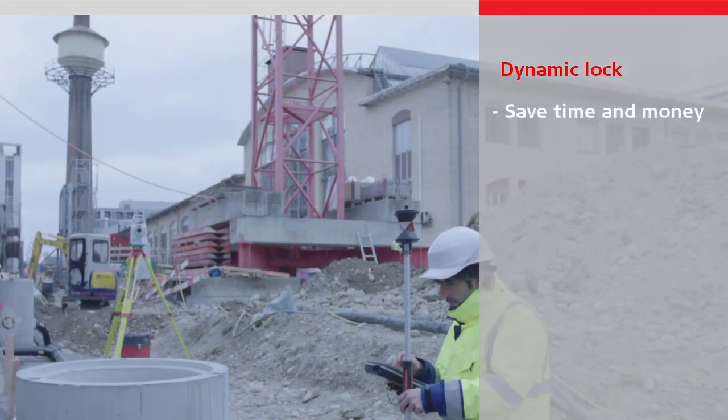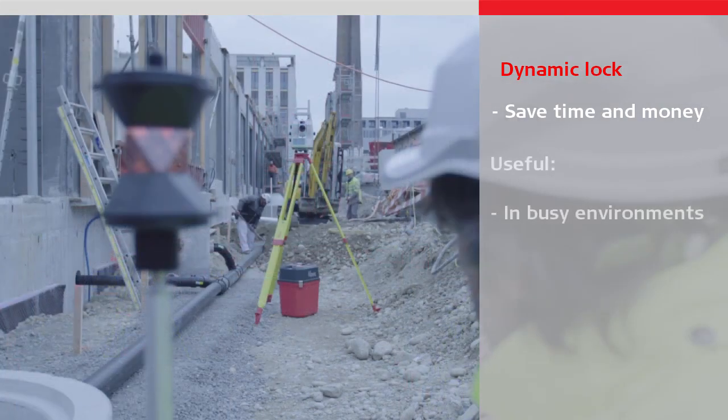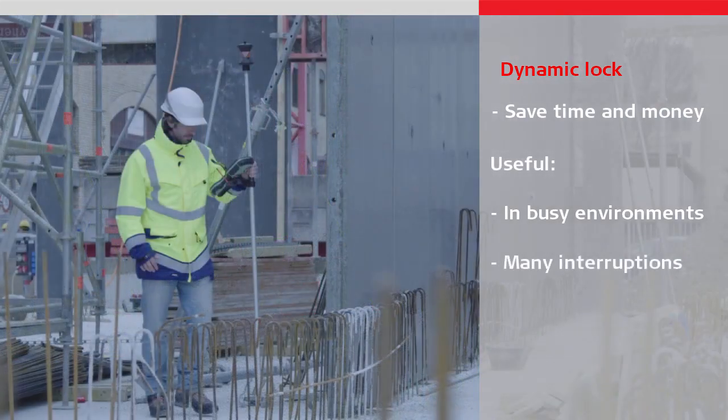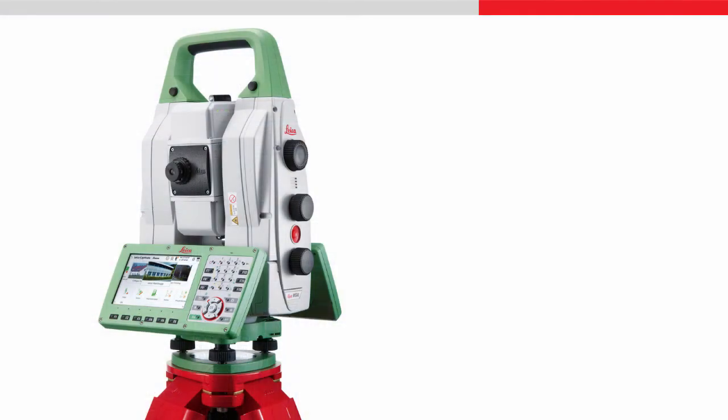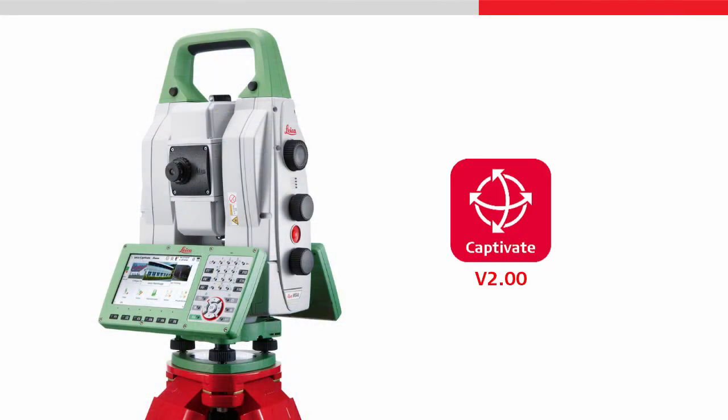It can be particularly useful when working in busy environments where there are many interruptions in the line of sight to the target, and the target needs to be repeatedly and quickly located. Dynamic lock is only available on MS60 multistations using Leica Captivate version 2 or higher.